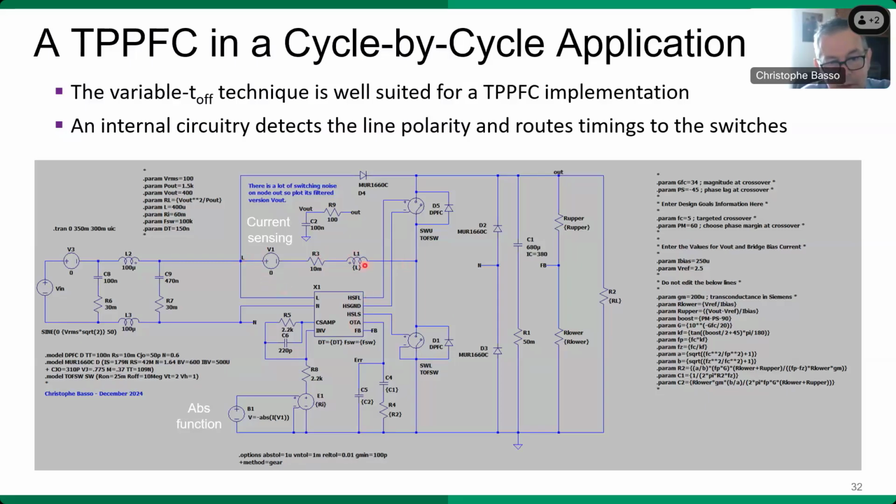You can see the inductance, which is here, floating, connected directly to the input source via a filter. I could have a Hall effect sensor here, and I'm sensing the current through this technique. I'm taking the absolute value, because I need to always have positive information, and it's going through the amplifier here. And I used a simple diode bridge that I can later complexify to deliver, of course, a low frequency synchronous rectification pattern for these two diodes.